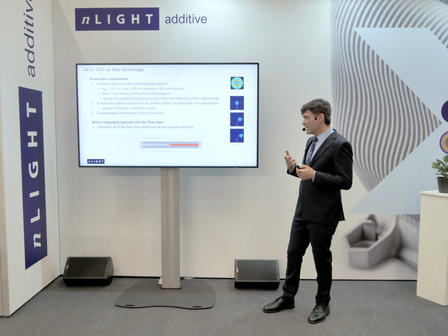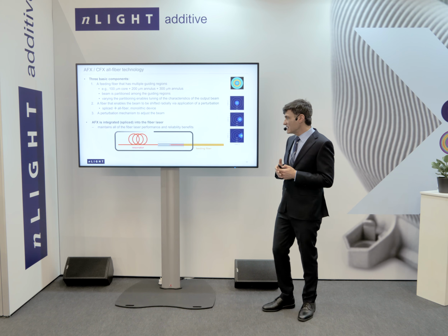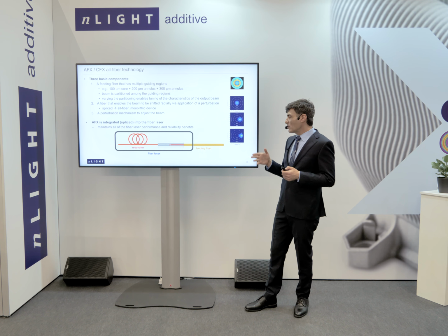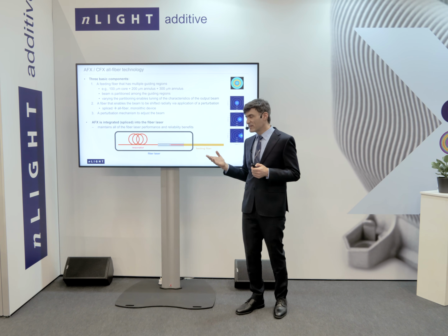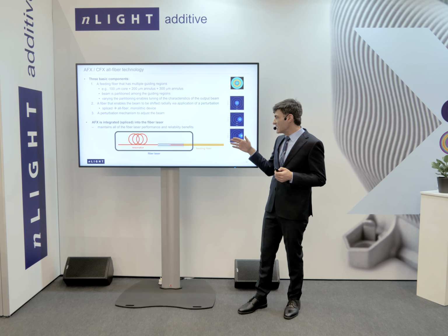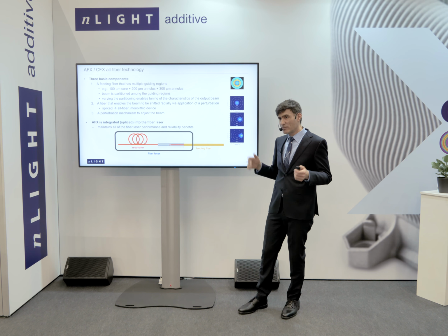This device is then integrated into the fiber laser by splicing it in between the laser cavity itself and the feeding fiber, and so it retains all of the fiber laser performance and reliability benefits. This is still an all-fiber monolithic train. To the end user, it's invisible that this is there, except that it has this magical beam tuning ability.